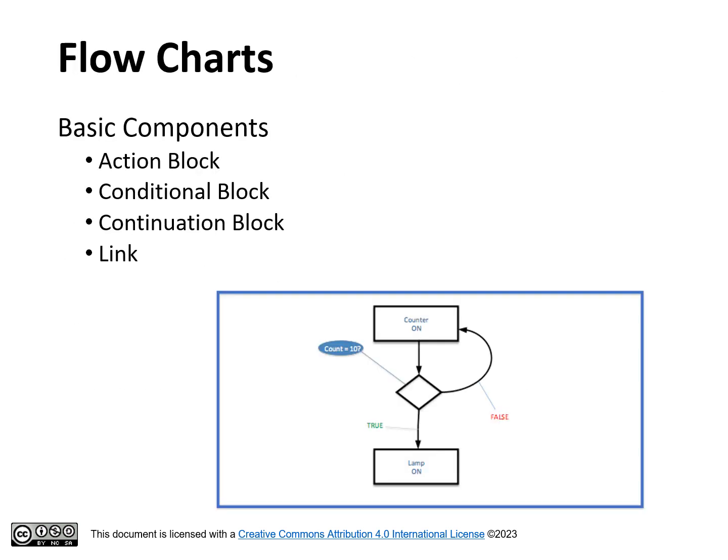The flowchart model utilizes flowcharting to design the control logic sequence. A standard flowchart is made up of the following basic components: action block, a rectangle with a list of command instructions. Instructions may include calculations, events, actions, triggers, and so on. Conditional block, a diamond shape enclosure with conditions that must be satisfied to direct the logic flow. Such conditions must yield one of the binary values, true or false.